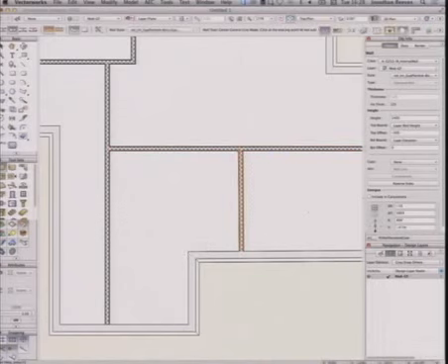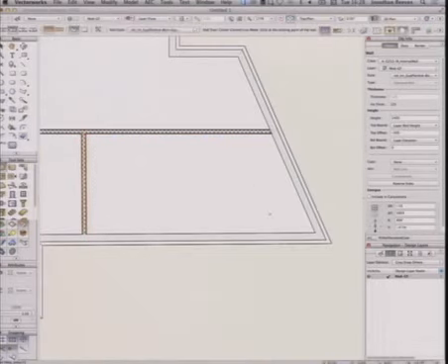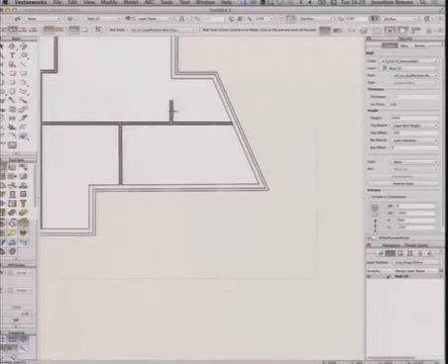So it's a very nice little tip. Without having to draw a line, then offset it and trace over the line, delete the line. We literally just hover over a point, hit the G key, and then tab, tab, tab. Let's go 1 meter, click. So I kind of start from 1 meter away in any position. So that's a nice little tip for you.